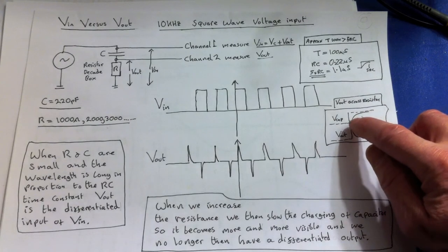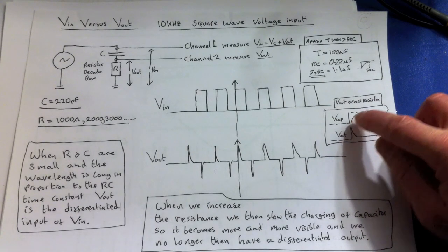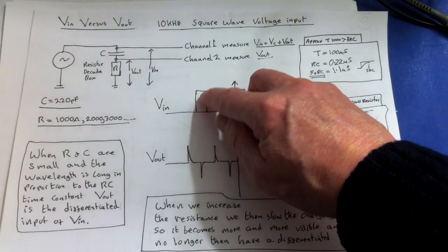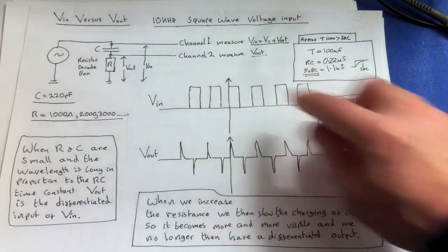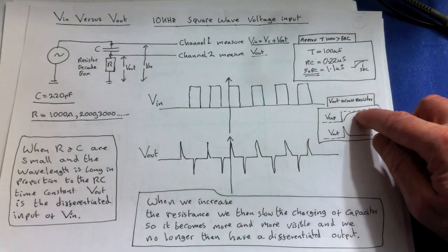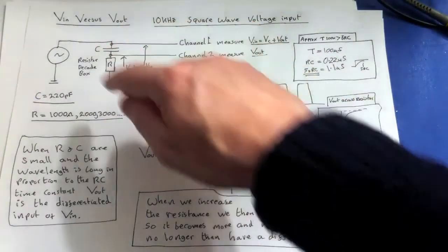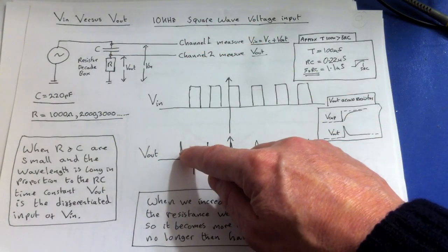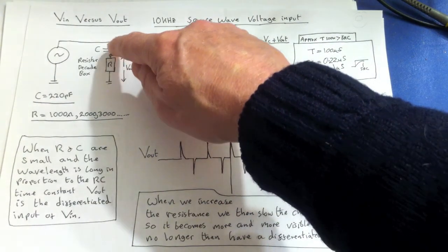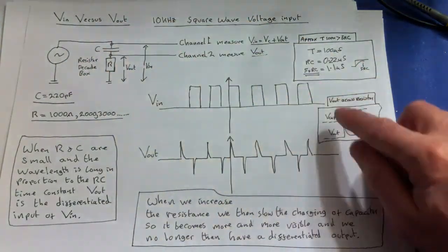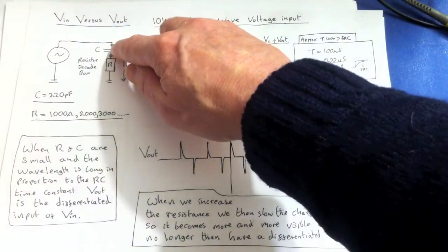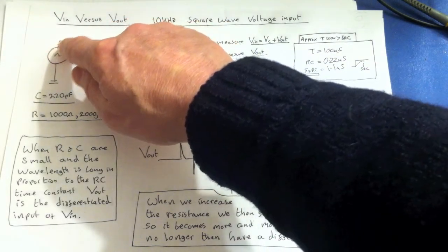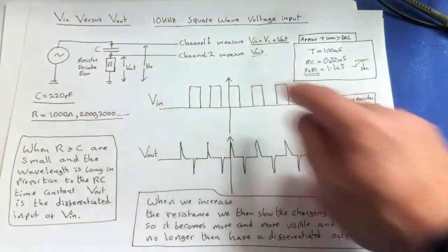When the capacitor is charging, we get this typical RC charge curve here. So at the square wave here, the capacitor itself is doing this, and we're not showing the capacitor voltage, but we know that the voltage dropped across the resistor is, for example, at the beginning here, there's no voltage drop across the capacitor. So if we imagine we just switch this on, at the very first instance there's no voltage across the capacitor.